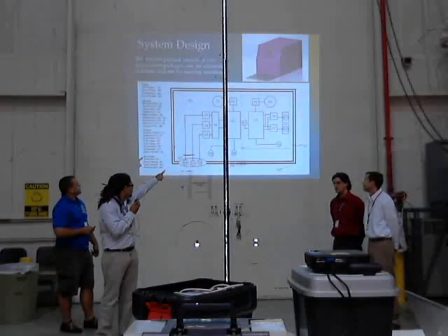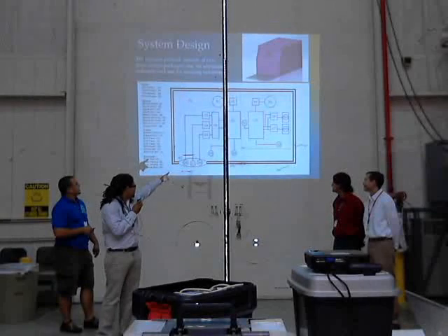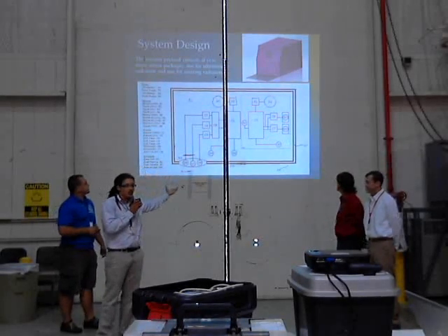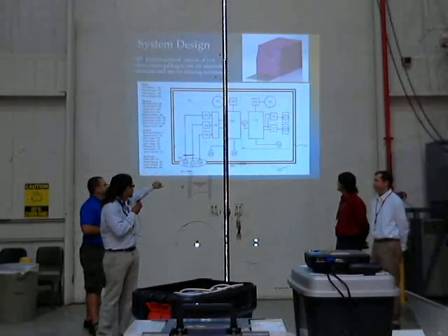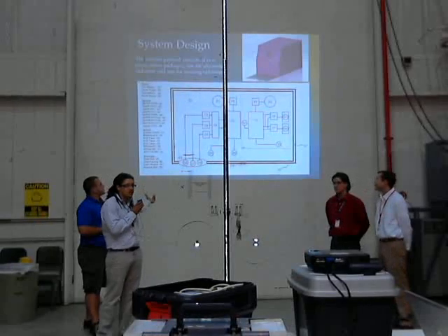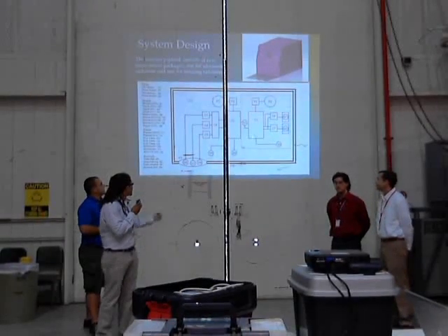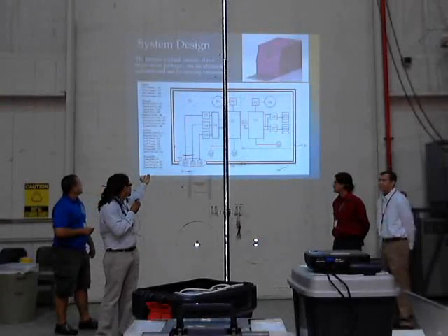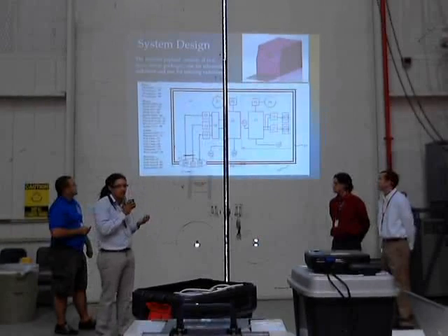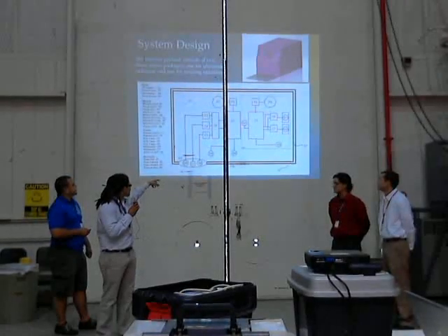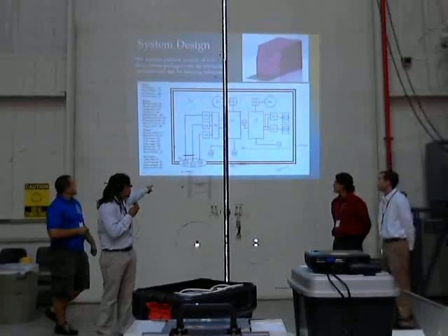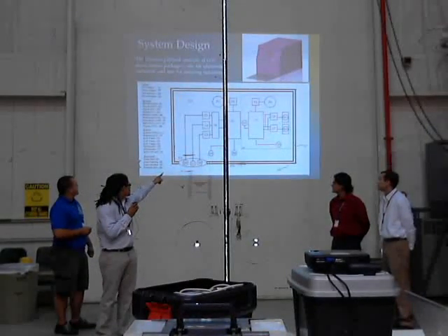Basically the sensors are temp sensors. We had two for each one: internal temp of the Arduino board and external temp. One was to measure the resistivity of our actual sensors as a function of temperature. For our UV, we added a 16-bit A to D to get higher resolution, which is C8, and they just get data from the sensors down here and send it to the Arduino.